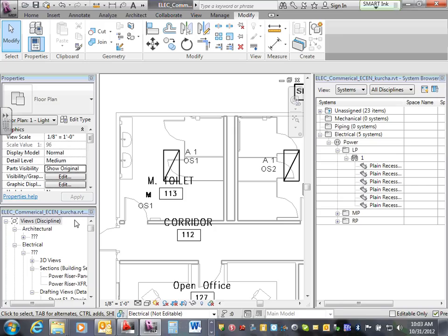Good design. I know based on visual, you need one. Good design, drop two, guys. When you come to red line with me, I know we need one. It's a good design to drop two. So I can grab this one, put this one here and another one right here. It's a good design in a bathroom to have two fixtures. Did you guys hear me? Even though visual said one. Not a big deal. You don't have to go change it in CAD, in visual. Right in here, you can drop as many as you want. Remember, this is a guide, and orient them appropriately. Especially in the bathrooms, it's a good idea to have two fixtures.